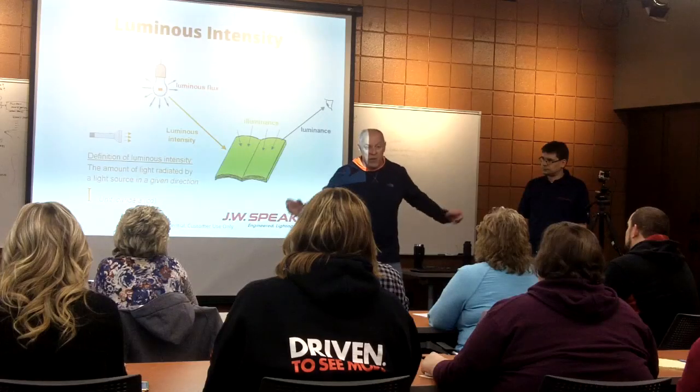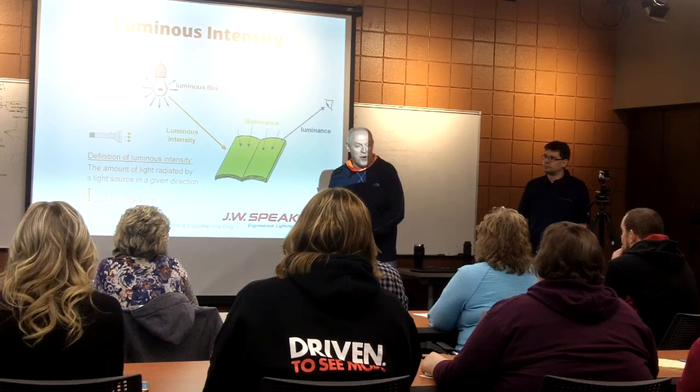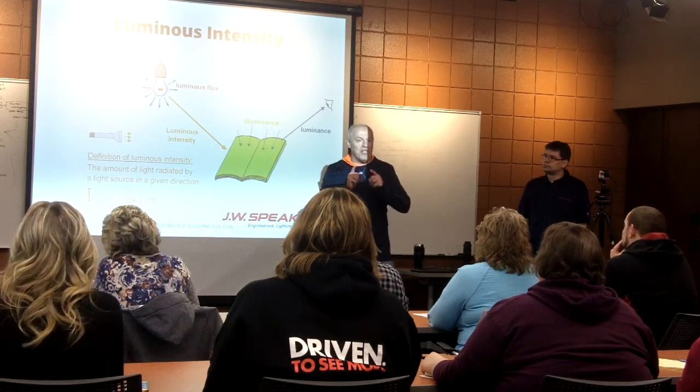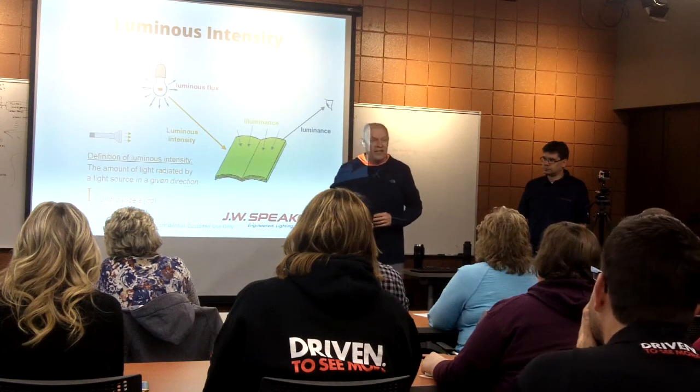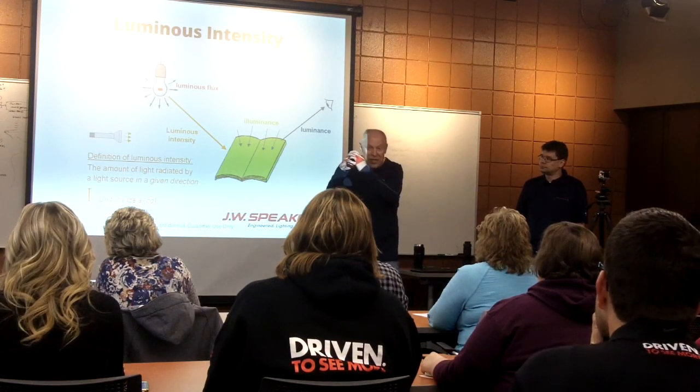That's why that source is only 5% efficient. All that work and all that energy goes just to energize that filament to emit that light. HID, it's like two electrodes. So you've got the two electrodes sparking in between, and there is a gas, xenon. That's why they call it a xenon lamp. It's just because of the gas inside of that globe. So that spark, that arc, emits the light. And that's the HID.